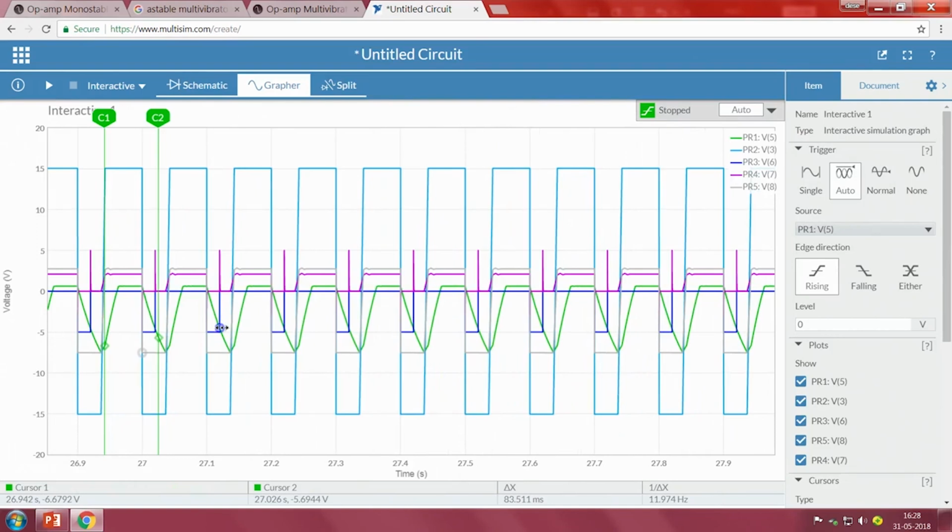So that means a monostable multivibrator is not continuously generating a square wave signal; the user has to provide a triggering input to the system, only then it goes to the minus VCC state. Then the capacitor starts discharging, and whenever the voltage value falls below the reference value, it goes back to its original state.